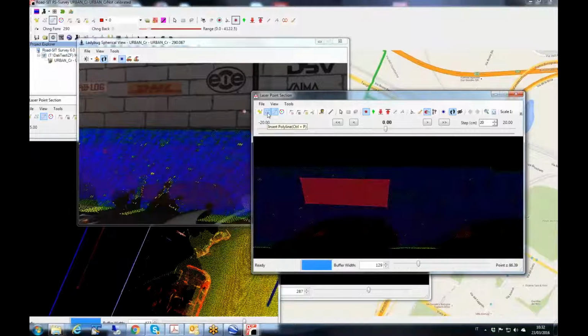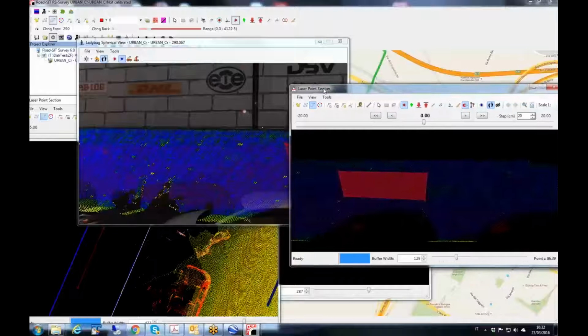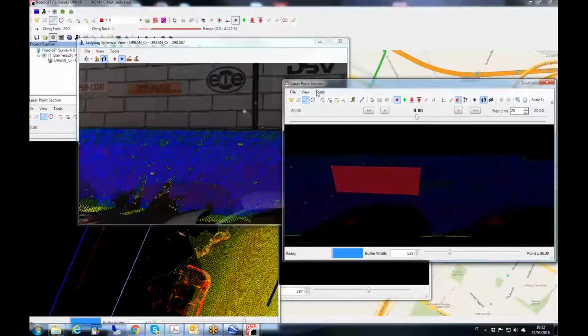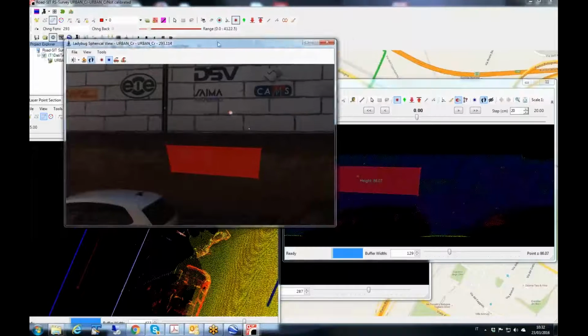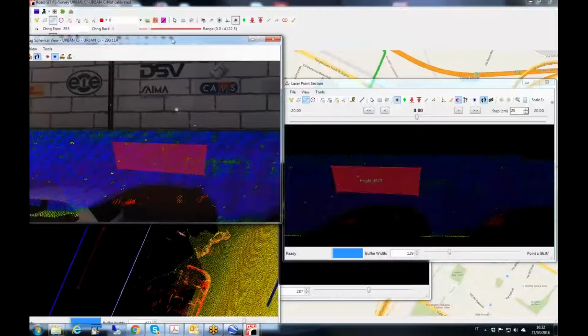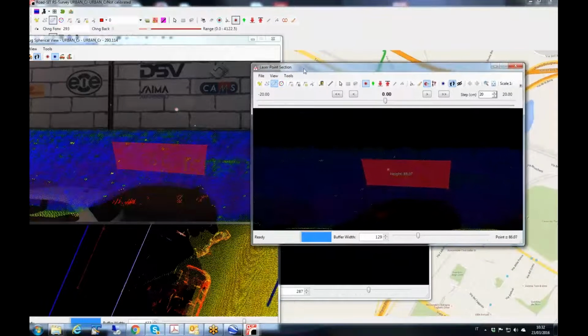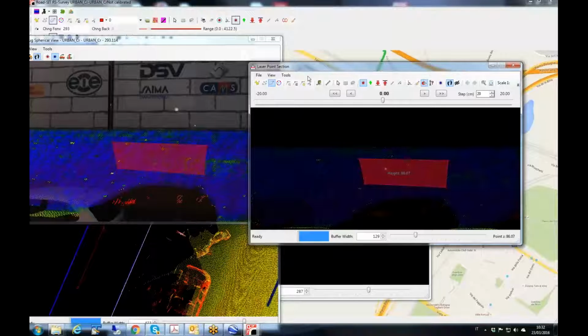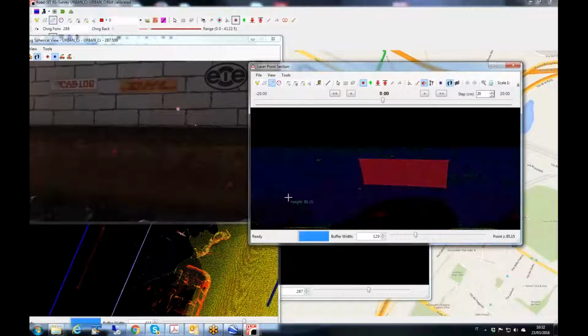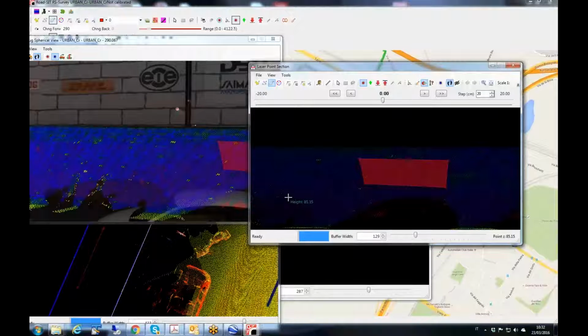So when we draw a forest or grass or a house, we have to use hatch. It should be like an area. So is it possible to draw areas directly inside the Roadside survey as a standalone version? No. But if you use the AutoCAD plugin, you can enable the hatch command in AutoCAD and pick points on the plugin. So the result is that you have the hatch in AutoCAD from the points picked in the plugin.